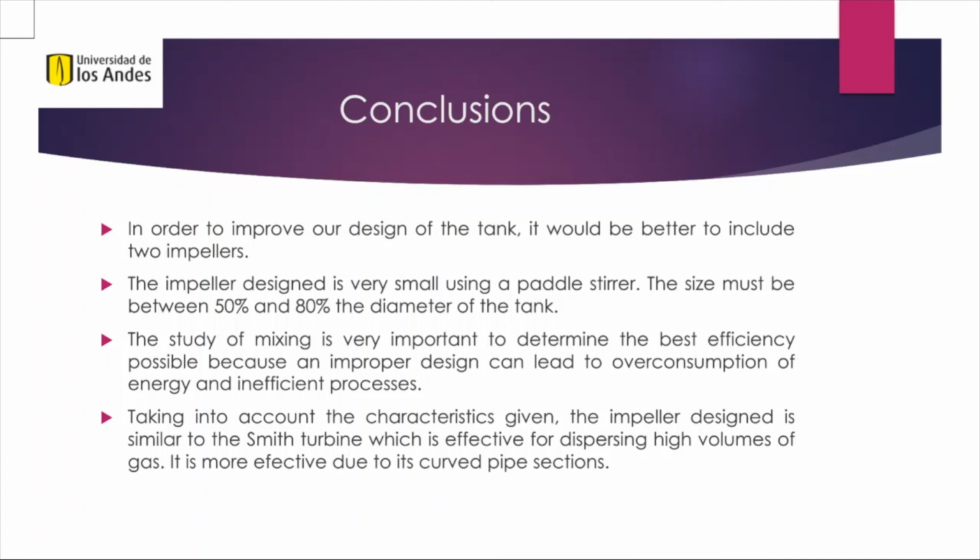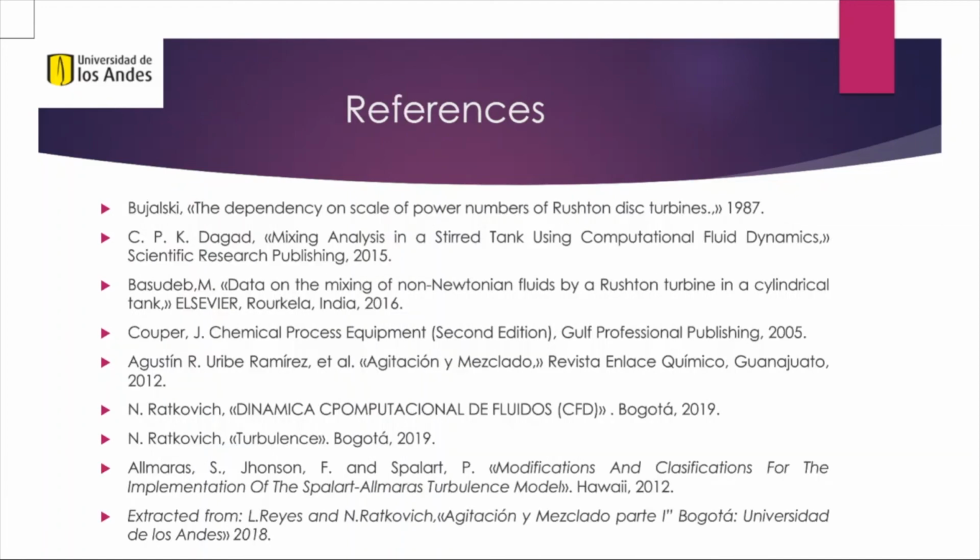Taking into account the characteristics given, the impeller design is similar to the Smith turbine, which is effective for dispersing high volumes of gas. It is more effective due to its curved paddle sections. The results obtained were very similar to the ones of the literature. This good comparison indicates the validity of the new model.